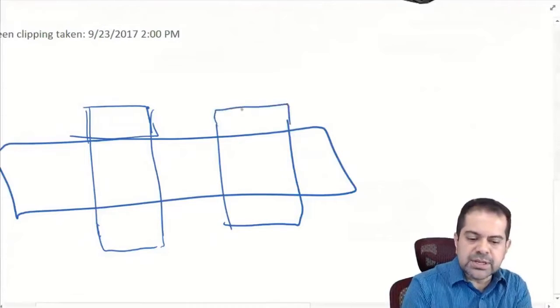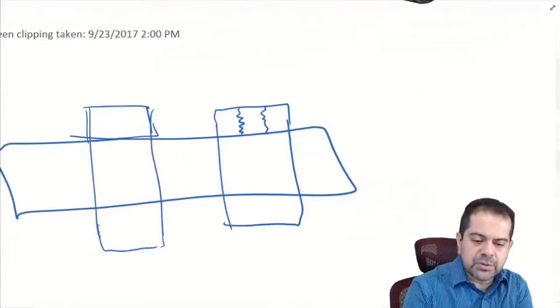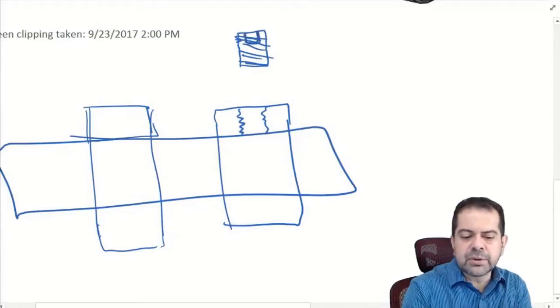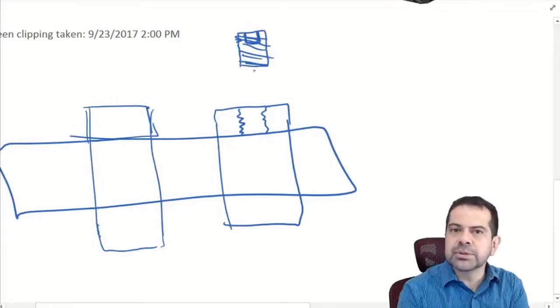It uses a set screw, so it's got a threaded hole, and it's got a set screw, which looks like this. That's off center, but it's threaded on the exterior. It's got a socket drive where you insert an Allen wrench or a hex drive to turn it, and it's got some sort of a tip. Not all set screws are the same.